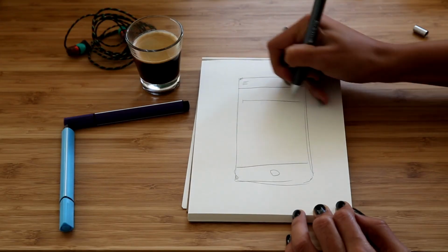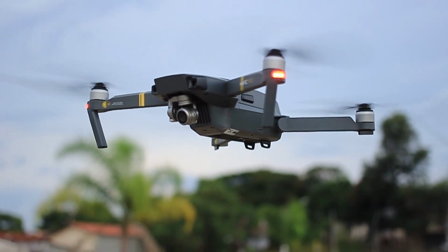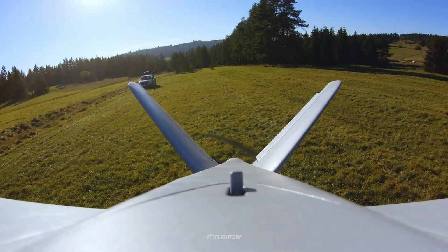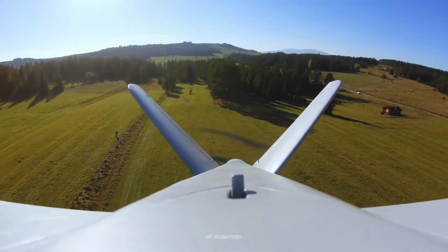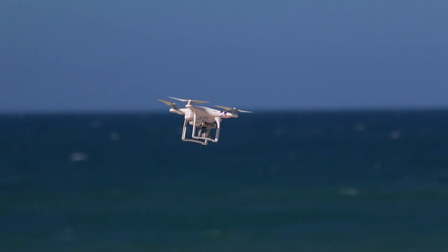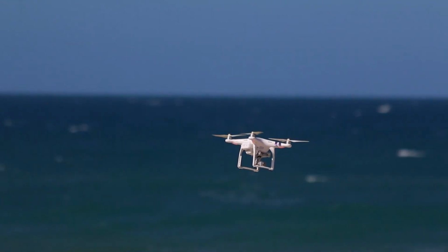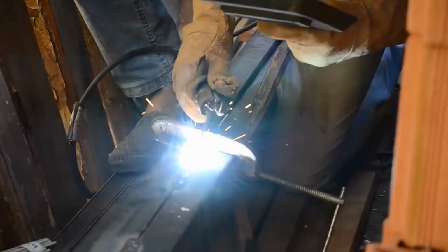Which drone works best for you? Need to hover? Choose a multi-rotor, a quad, hex, or octo. Need long range and efficiency? Look for a fixed wing or VTOL. Need to be stable in wind? More rotors or a fixed wing. The more aerodynamic surfaces, the more stable you are. Need agility? Quadcopter. Need a heavy payload? Fixed wing or octocopter. Every drone type is engineering built for a specific job. Understanding why they are different helps you pick the right tool.